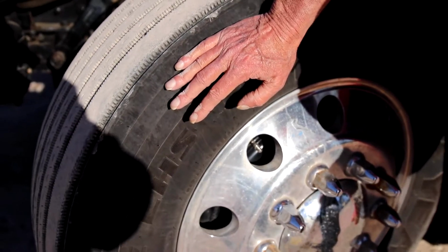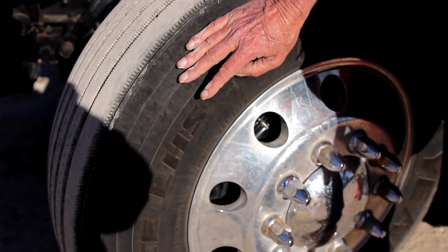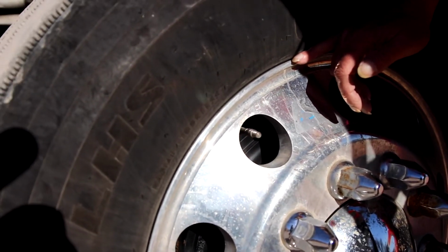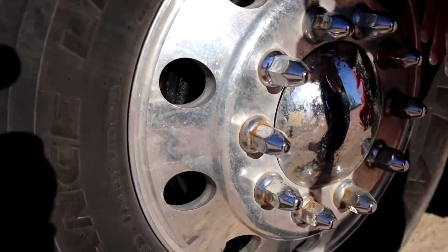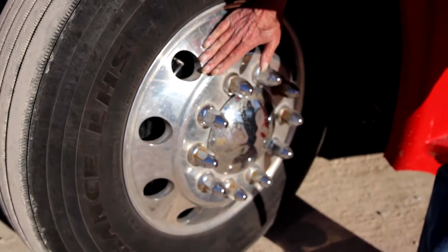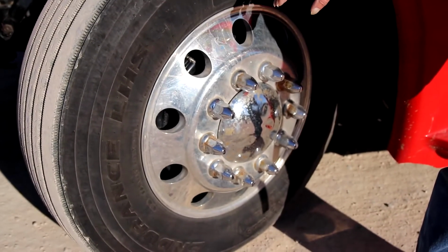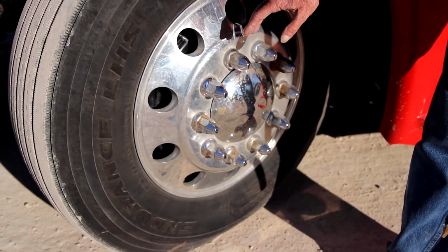My outer side wall has no abrasion, bulges, and cuts that could cause a blowout, and it's mounted securely to the bead of the rim itself. It is not damaged. My outer rim is not damaged, no illegal welds, no bends or breaks.